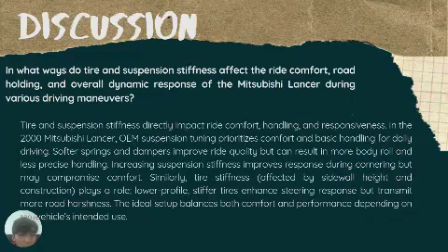Softer springs and dampers improve ride quality but can result in more body roll and less precise handling. Increasing suspension stiffness improves response during cornering but may compromise comfort.